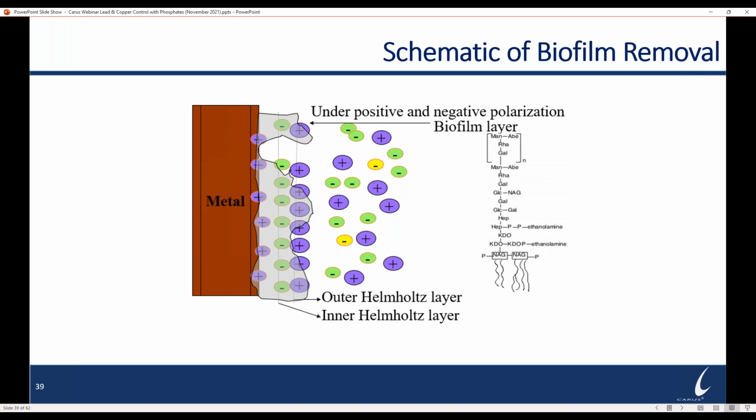The idea here is slow and steady wins the race with your dosage. So in a distribution system, you would just feed your normal dosage for sequestering along with your normal dosages for chlorine and monochloramine, and you'll get some of this cleanup of the system slowly over time.